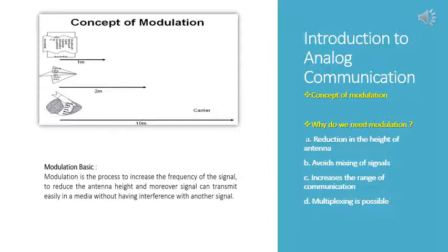So we have a similar concept in our communication system in the case of modulation. Here, we simply modulate a basic baseband signal with a carrier signal. The baseband or message signal has a very low frequency, around 20 hertz to 20 kilohertz. We modulate it with a carrier signal which has a frequency in megahertz, merge the two together, and send the information towards its destination.